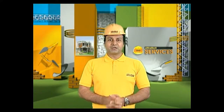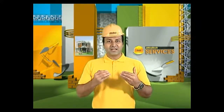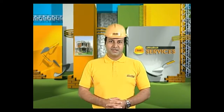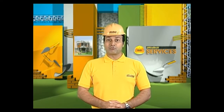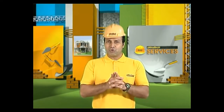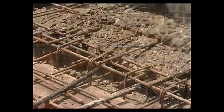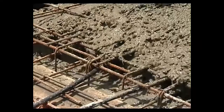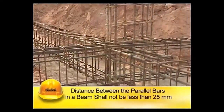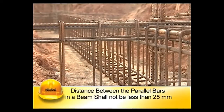Detailing of reinforcement assumes greater significance as poor detailing makes an elaborate analysis worthless. Good detailing ensures that the reinforcement behaves as designed and the structure will become strong and durable. There should be sufficient horizontal distance between the rods so that the biggest size of the aggregate in concrete can pass through. The distance between the parallel bars in a beam shall not be less than 25 millimeters.